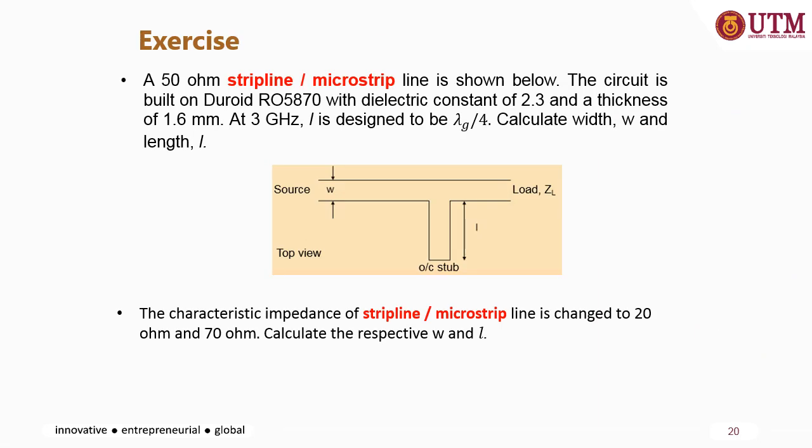For the earlier example, you can also compare your calculation with the graph. You can refer to the Z0 versus W over H, so you can compare your W over H value with the one you have calculated.